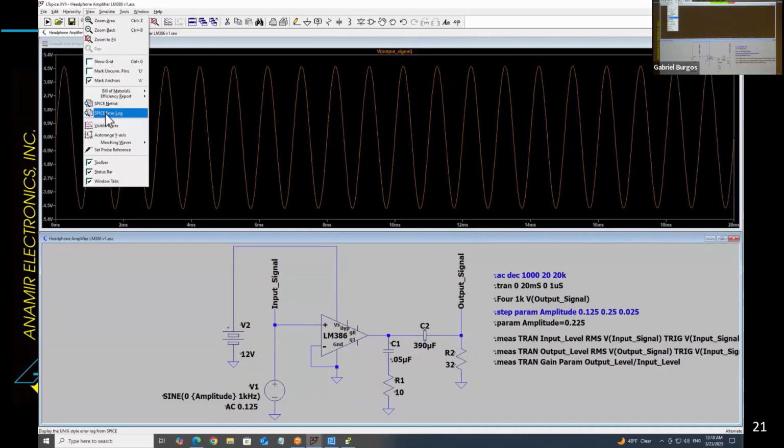I had to go to some special lengths to make a model for a floating amplifier. My synthetic transformer isolation technology involves operating the op amps on floating power supplies compared to the destination ground reference. To model that is a real trick, because you have to have pathways back to ground, or else LTSpice is unstable and won't find solutions. So I had to make my own op amp models, which could work in what is virtual isolation.